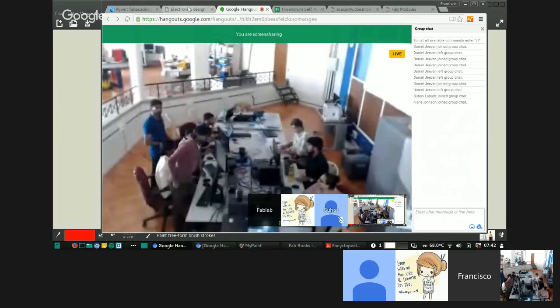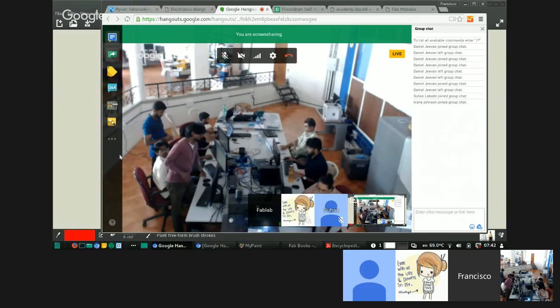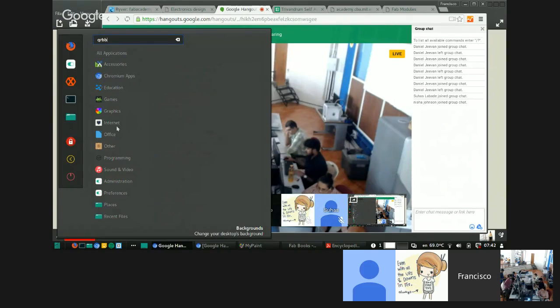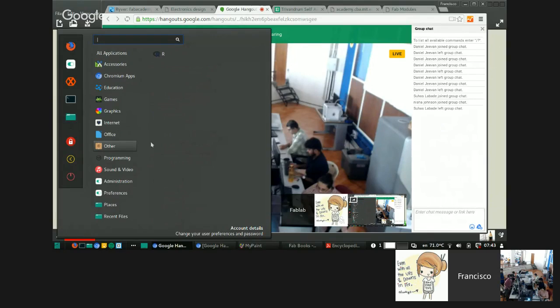Yeah. So there's a tool called gerbv in Ubuntu. Frank, you heard that? Yes. What is the tool? gerbv. Okay, so from that tool you can view the Gerber files, and then you can export it as a PNG. It has options. Is it like a command line tool? It's not command line. It is a GUI based tool.